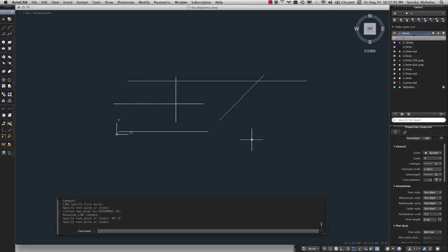And the thing is, when we draw in AutoCAD, we always draw lines to the real world scale. Okay, you don't scale your drawings when you're working in this model space. You draw things in the actual dimensions that they are. I'll show you in a minute how, when you plot, you're going to change the scale to quarter scale or half scale or 100 to 1 or 200 to 1, okay?